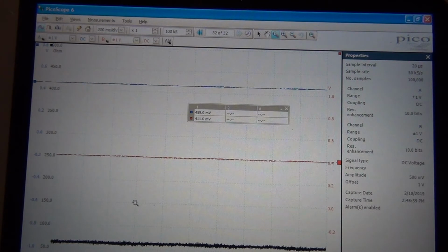So we are done here. It's showing us the trace, which is approximately 60 ohms, just as we wanted. So our CAN bus physically is intact, and we have two terminating resistors that are giving us a 60 ohm value. Perfect.